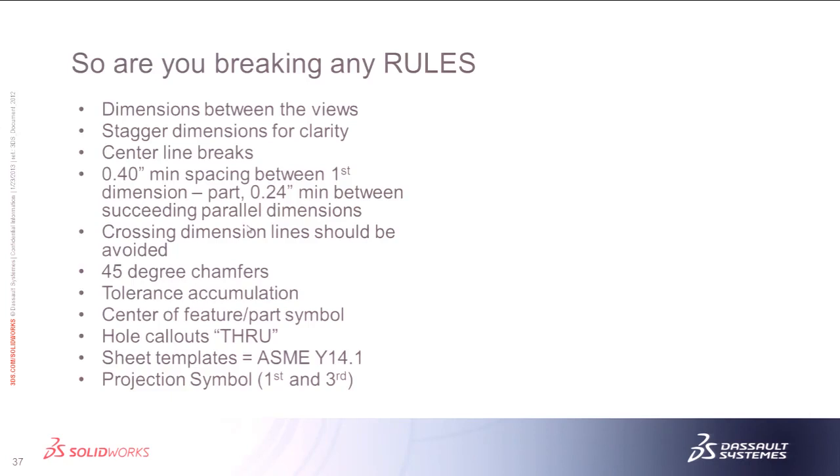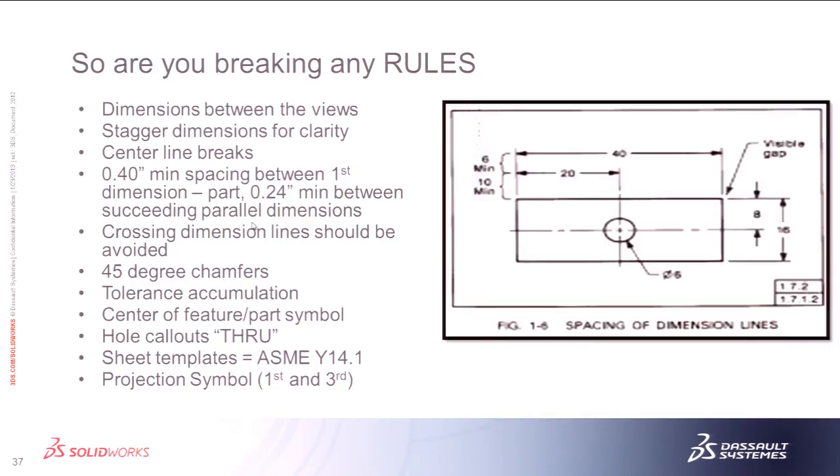I want you to avoid crossing dimension lines. Basically, when you can avoid it, you don't want the 20, the small dimension, over the top of the big dimension. So you don't want to cross dimension lines unless you have to. There are many, many times where you have to. Just try to keep it to a minimum.